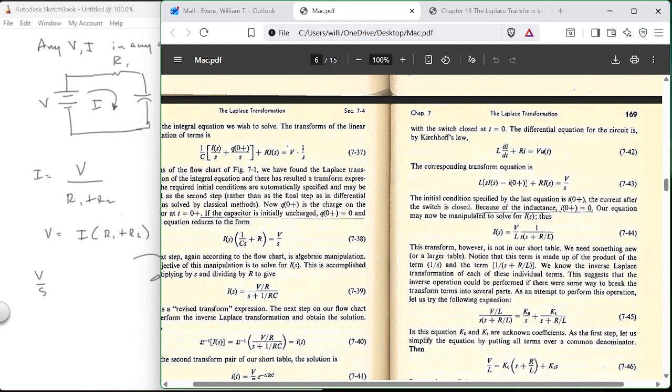Anyway, you can use it on your PE test. And once in my life, I actually walked into a situation where I said, how does this thing work? And right here it is. This is the answer to how an L and a C, only two, go at a frequency. And you can explain it from this circuit, right? You can build a circuit with a DC supply, and it works like a high frequency device. And that's how a metal melter in a factory works. One of the ways you can melt metal is right here.